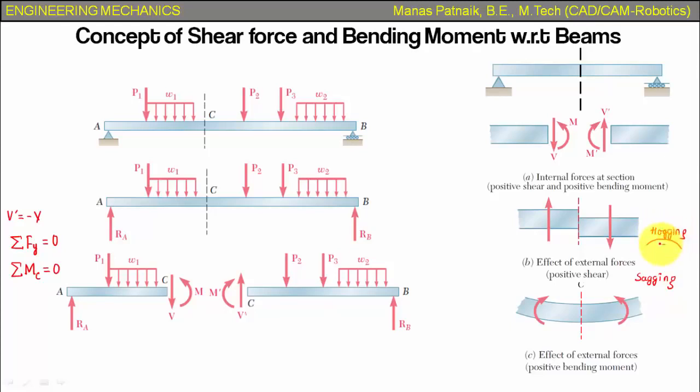And this has negative bending moment, and when you speak of sagging, we have a positive bending moment. So guys, essentially you can solve the problems based on beams in both ways. You can take the section from the left or section from the right, but the most important thing in this lecture up till now is this sign convention. Okay, so copy paste this sign convention in your mind so that you're able to solve each and every problem based on statically determinate beams.